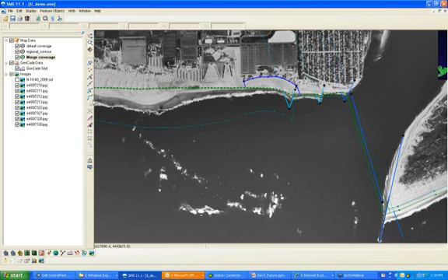So we'd go ahead and click again on this Create Feature Arc. And say for some example you wanted to protect this area of the shore. We could just draw a breakwater. So we draw one point and then double click. So this probably is not going to be where you'd actually have a breakwater or the distance offshore or the distance of the breakwater. But I just want to go through this, show you what it looks like, and then also really exaggerate it because I'm making this probably larger than you would make your breakwaters.